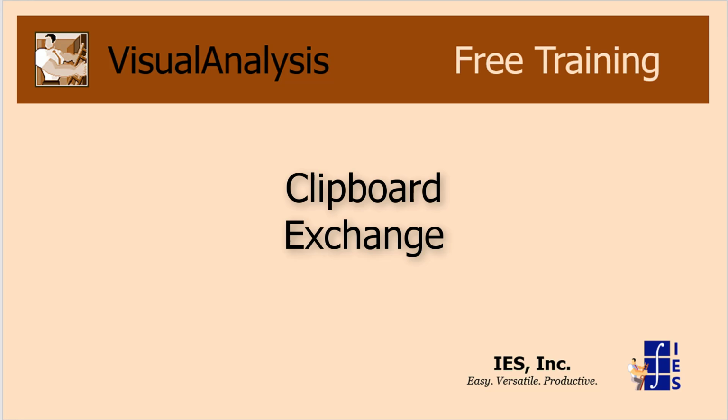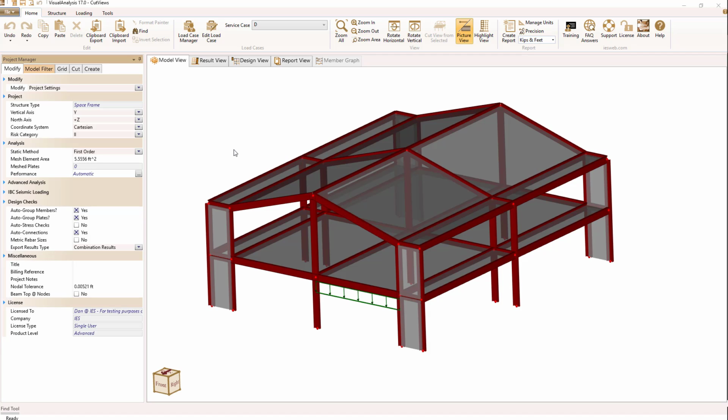Clipboard Exchange is a very powerful tool in Visual Analysis and allows you to do some very complex modeling things. Let's look at how that's done. I have a simple structure here which has beams, columns, a member load, and some plates.